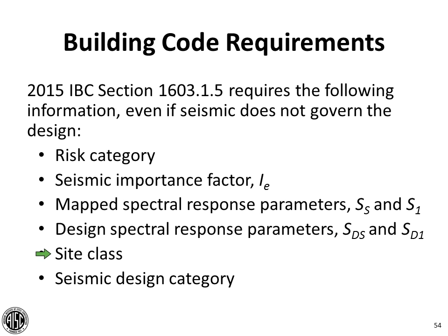Then things such as the site class, that is, gives you some sense of what kind of soil, and then ultimately the seismic design category, which is important in terms of determining whether or not a project must follow the requirements of AISC 341, or if there's the option of resisting the seismic forces by following the requirements only in the main specification, but having to design for a much larger seismic force.